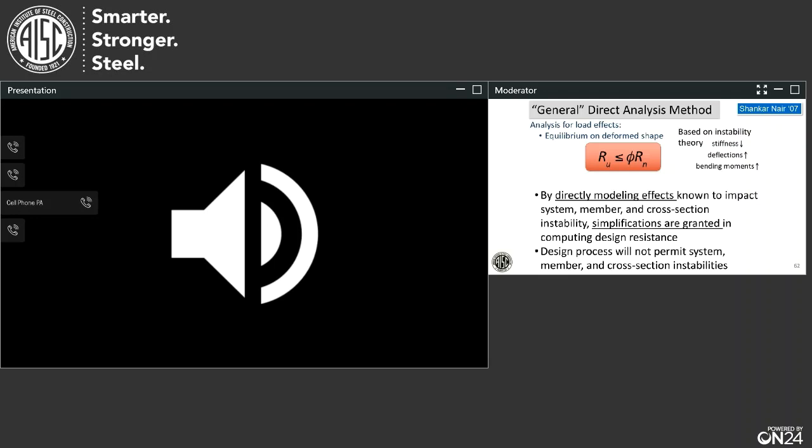So I may have just made a case for going with the effective length method, but what I'm really saying is the direct analysis method should default to the effective length method in a truss. You say, well, what about that 0.8 on E? The direct analysis method says I need to have it there. Go ahead and put the 0.8 in your truss analysis, or don't. You'll get the same force distribution. It's not going to have a big impact because the truss is so stiff. It's very rare that we have second-order effects. When we will get second-order effects in a truss is if it's a tall, slender truss. Then we've got to scratch our head.